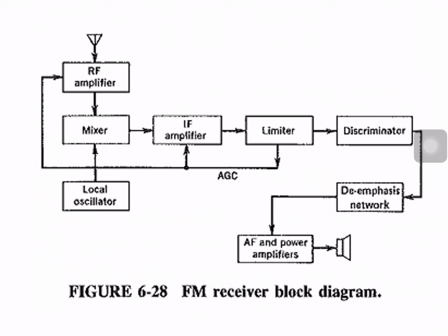This is because the tuning frequency range is only 1.25:1, much less than in AM broadcasting. So a very satisfactory arrangement for the front end of an FM receiver consists of FETs for the RF amplifier and mixer, and a bipolar transistor oscillator. As implied by this statement, separately excited oscillators are normally used with some basic arrangements.